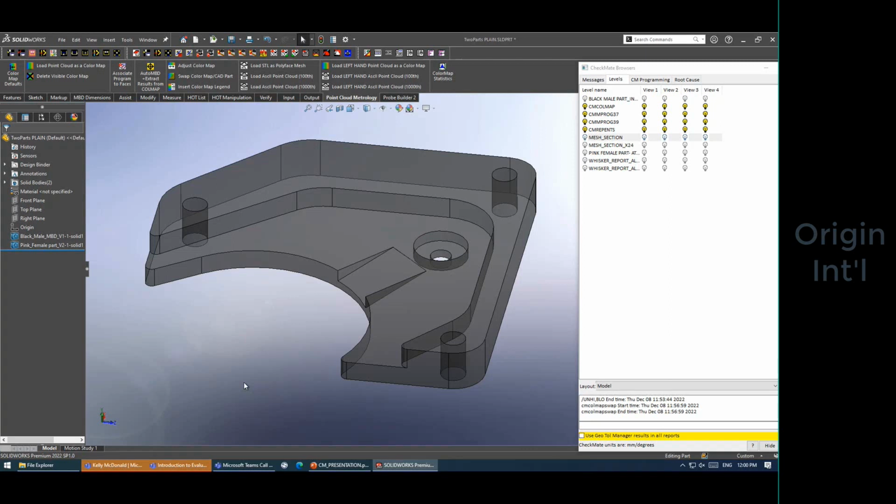That's right. Yeah, Jim, think of a car. If you have the full assembly of the car, it's going to have its own datums, A, B, and C. Probably the center of the car, the front bumper kind of thing. That's kind of where 000 is for a final assembly. But if you take a component like a rear view mirror, its A, B, and C is going to be completely different than the A, B, and C of the final assembly of the car that it attaches to, unless they did it a little bit smart and everything relates back to car zero or truck zero.